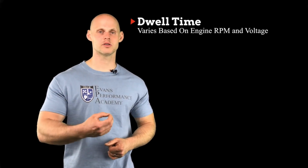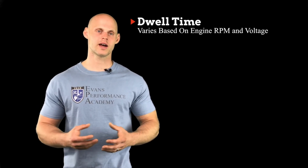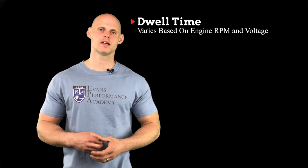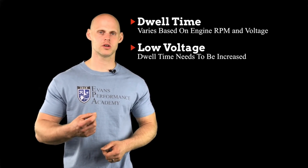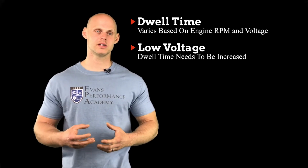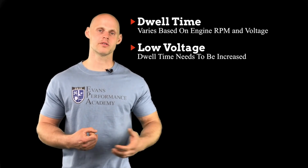Now, another thing to keep in mind with coil dwell is that it's going to vary based on engine RPM as well as battery voltage. So if our charging system or our battery goes down to 8 volts, it's going to take longer for the primary windings to charge in order to reach that 5 to 7 amp saturation point. So it might take an extra 2 milliseconds of coil dwell at a very low battery voltage.